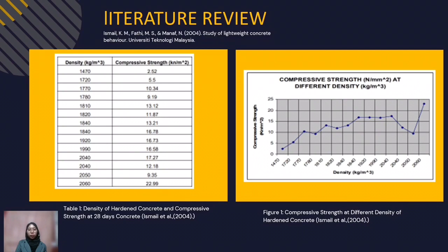The required compressive strength of lightweight concrete is 3.45 MPa at 28 days as a non-load bearing structure. The compressive strength obtained from this mixture is higher than 3.45 MPa, and therefore it is acceptable to be produced as a non-load bearing structure. However, the compressive strength for the mixture with a density of 2,050 kg/m3 is slightly low compared with the density of 2,040 kg/m3.